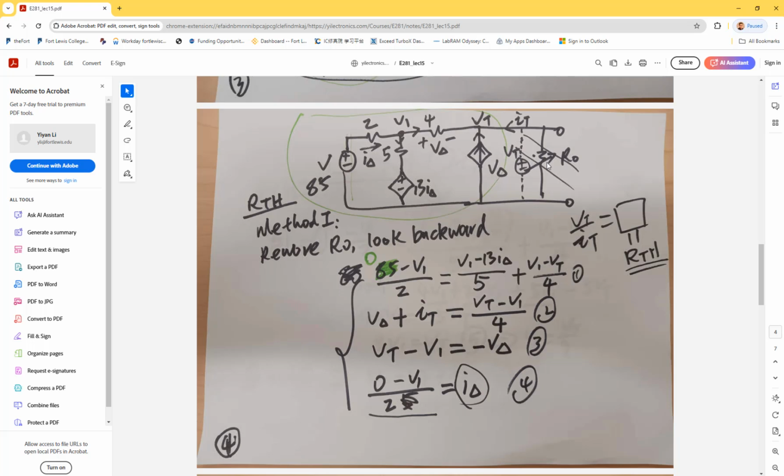Okay, since you are trying to calculate the internal resistance of the black box, the ideal sources still have to be either shorted or disconnected, but not the dependent source. The dependent source can be a lot of other things. They do not have infinite internal resistance like current sources or zero resistance like voltage sources. You don't know what's inside. It could be a current-controlled voltage source like a transistor or something else. It's not a standard resistance. So you are not supposed to remove any of the dependent sources.